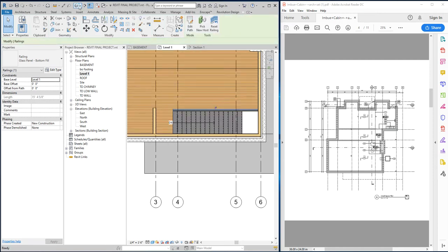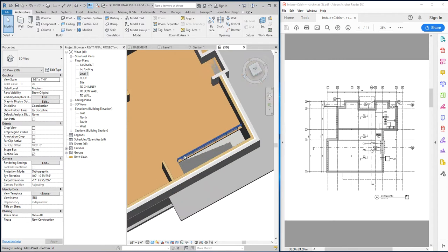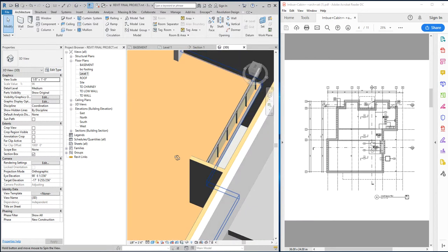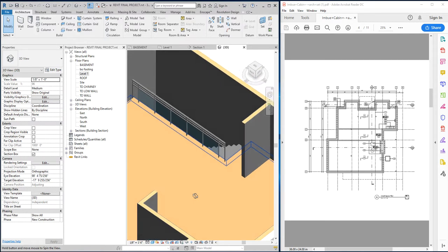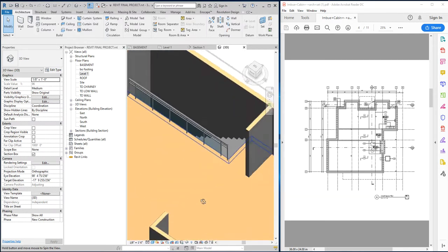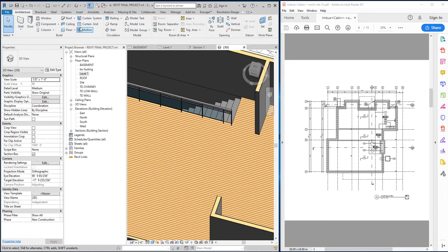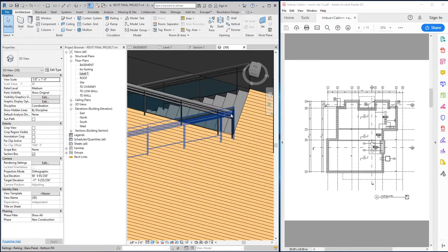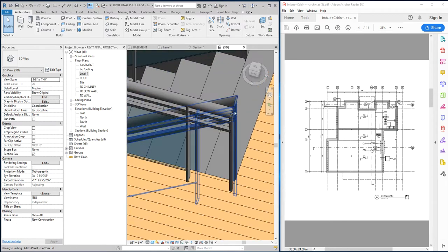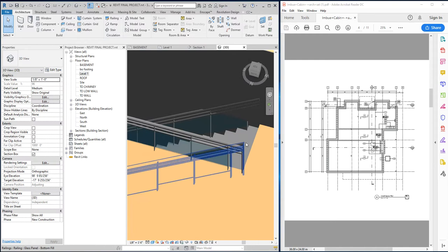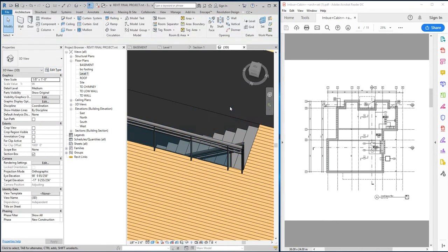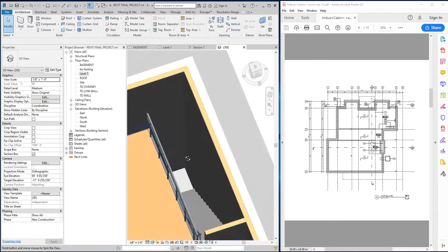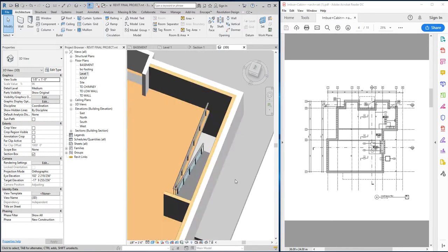Okay, so I can hit finish now. I'm going to pop into 3D, and I've got my lovely railing. Okay, I could, if I wanted to now, say, let's host one on, this one's a little odd without getting into some customization of railings. I'm going to do Place on Stair, click, and I could have it draw a little piece that sort of connects these two, draw a little segment right there, to connect those two going down. I could delete one side if I wanted, leave that side. Anyway, you guys kind of get the idea.